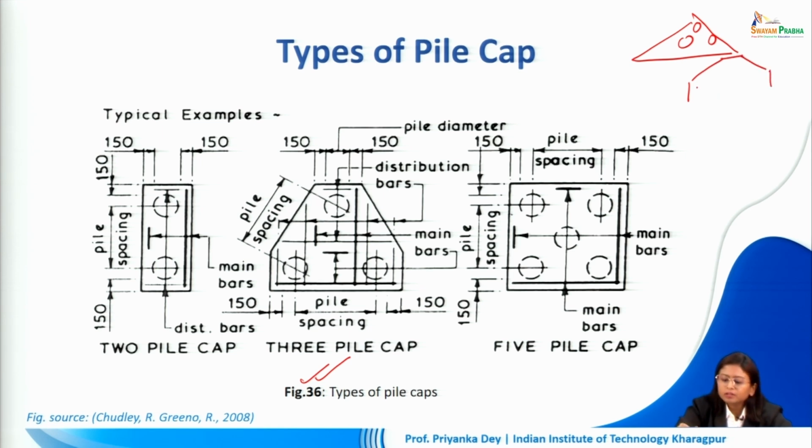Now why we are doing this split at the side is because it is very difficult for us to cut corners like this when we are dealing with foundation construction. This can become problematic during construction. It is much better to go for a chamfered edge, and it is created in such a way that there is sufficient cover between the reinforcement that is placed inside and the concrete. So a certain gap has to be ensured.